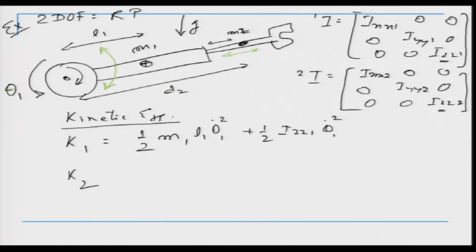So, this is very easy. This term is essentially coming from half m v squared, where v is equal to omega r, squared. So, omega is equal to theta dot, so you can see that it is theta dot r squared. Okay. That is where it is coming from. So, this is how we have half m v squared plus half omega I omega, that is where this term is coming from. So, we have two terms: the kinetic energy of the first link is equal to half m v squared, and half omega I omega, which is giving me this term.